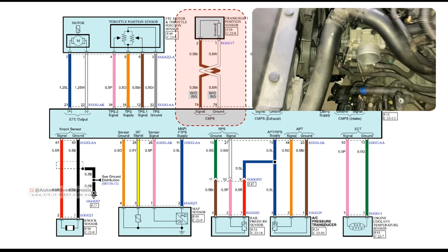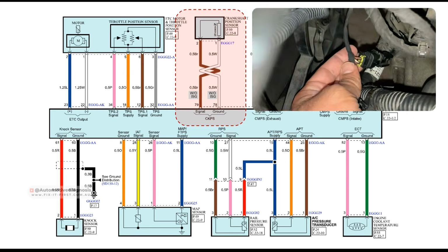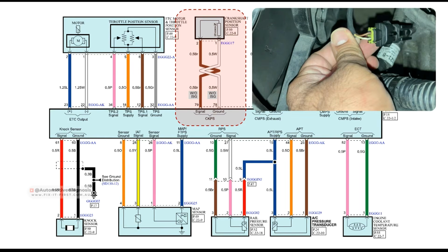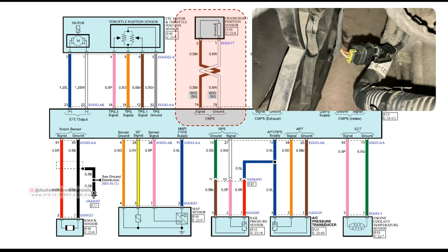For example, on this engine, the sensor is located at the rear side, but they made the connector available for everyone to do the diagnostic. Instead of just going under the car, you can reach the connector like that.